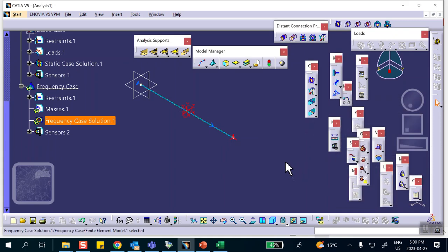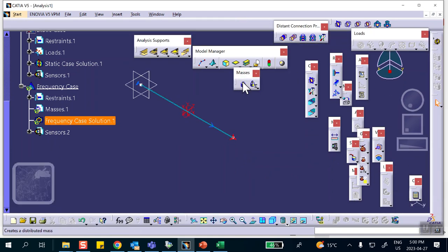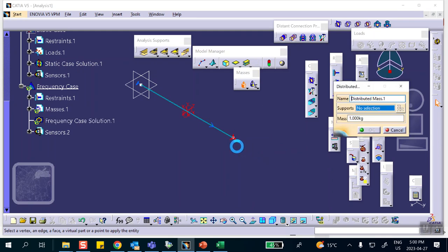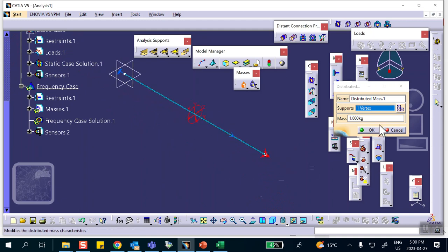So I did it right now. That's pretty much it. So if you run, oh, I forgot to put the mass here. There's a mass of 1 kilogram there. So look at the inertia or mass here. Here's the toolbar for it, right there, masses. Click on it. You select this point, and you put a value of 1 kilogram. So it's going to be a mass at that point. You can actually see that. See this? See the mass? Okay, it's just the icon for the mass.